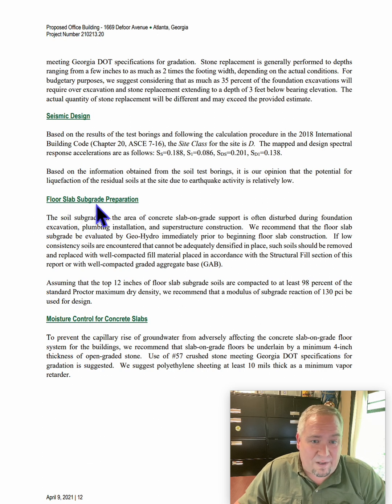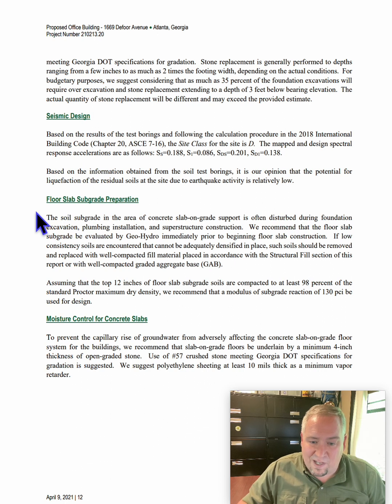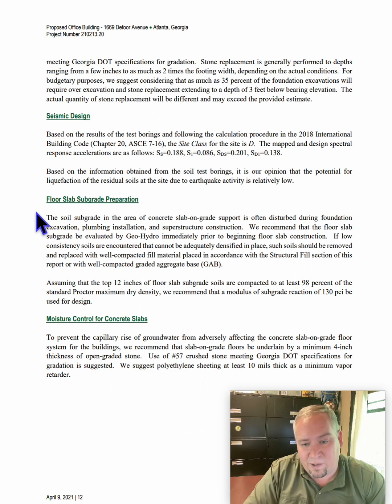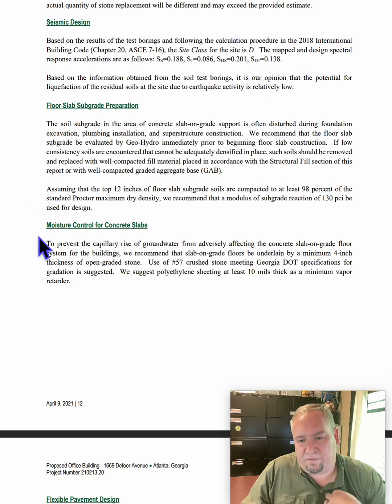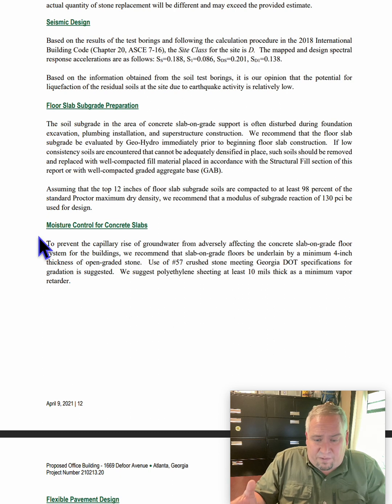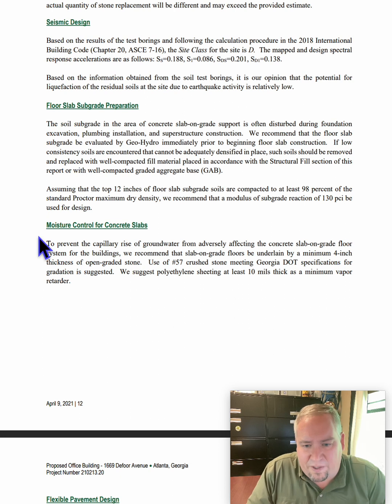Floor slab subgrade preparation. When we are going to prep the subgrade for the slab, we're going to read this and understand exactly what they're planning on doing and what expectations they're going to have, because we don't want to come out there and say, oh, we're ready, and they test it and say, guys, this is not what we had talked about. So read that section. It's very important to understand what you're doing. Let's see, moisture control. If you've got water tables that are fluctuating up and the ground is starting to wick up the water, you don't want all that moisture coming into the bottom of your slab and causing mold and mildew issues or anything like that.